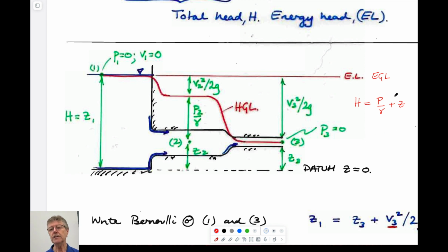When we solve the equations for flow in porous media, we don't care about the velocity squared term. We assume that v squared over 2g is equal to 0. So if you're flowing in porous media, typically the velocity is very small. Typically the changes in velocity are quite small, and therefore we neglect this term. And what's much larger are frictional losses in the system. You don't care about that now. So we define a thing which is hydraulic head.